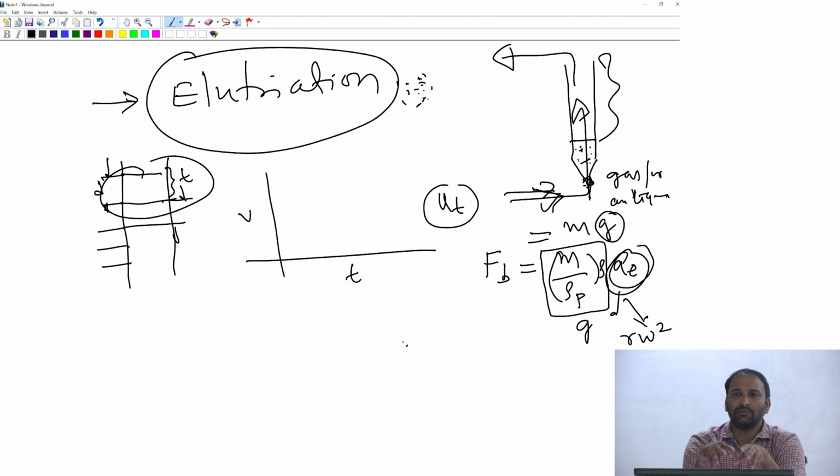So you should also think a little bit about working out the equation that we developed for cases of other particles. We looked at a simple case of a spherical particle, but you can also develop similar expressions if you're thinking about settling of, say, a cylinder. If I have a cylinder falling with this configuration under the influence of gravity, then your AP, the projected area, is going to be the area of a rectangle: your length times the diameter. So you have to take the appropriate AP, right?